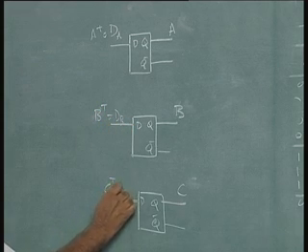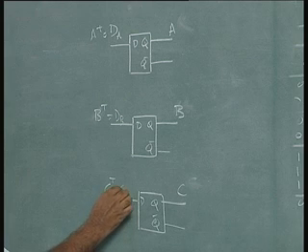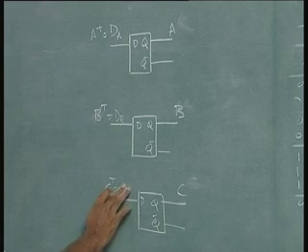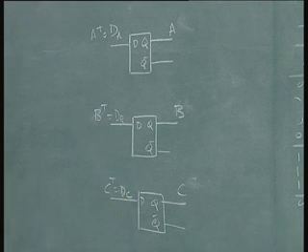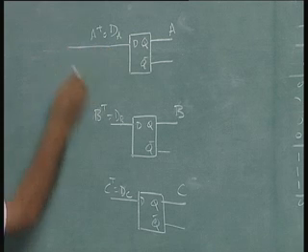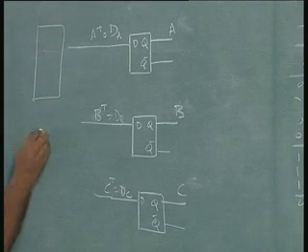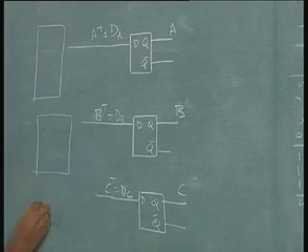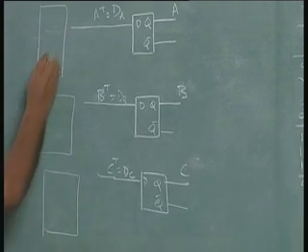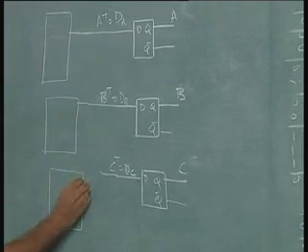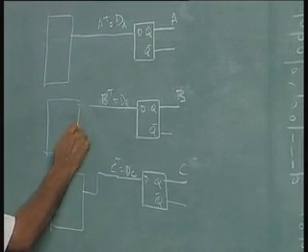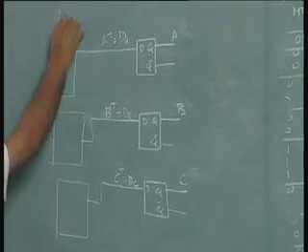I think we have done all these things again and again. See, we can't be going on doing these things in every problem. So, assumed architecture. So, each of these is given by a multiplexer, which is 8 to 1. And this is connected here, and ABC are the inputs, selectors.